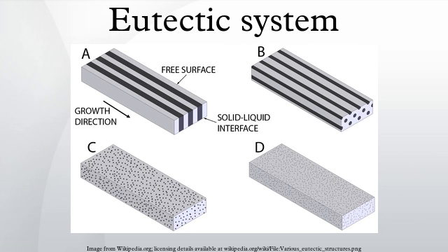Here, a liquid and solid phase of fixed proportions react at a fixed temperature to yield a single solid phase. Since the solid product forms at the interface between the two reactants, it can form a diffusion barrier and generally causes such reactions to proceed much more slowly than eutectic or eutectoid transformations. Because of this, when a peritectic composition solidifies, it does not show the lamellar structure that is found with eutectic solidification. Such a transformation exists in the iron-carbon system, as seen at the upper left corner of the figure.